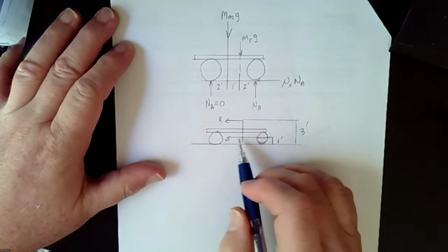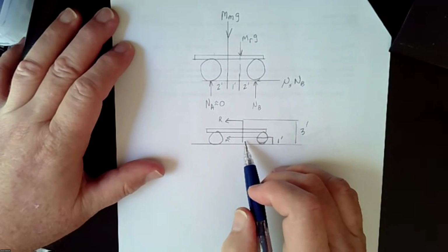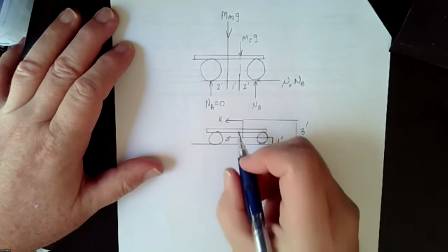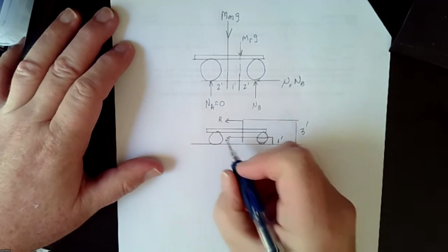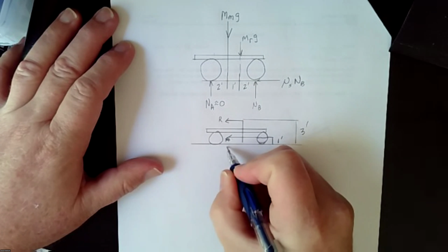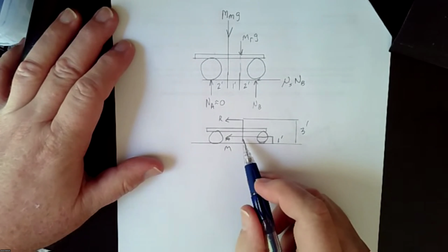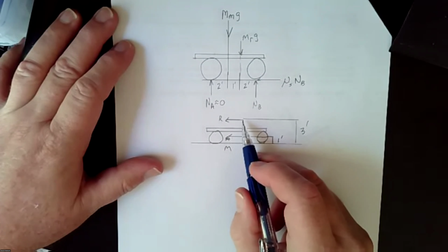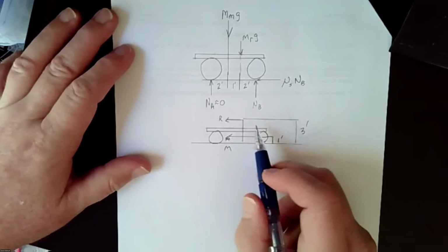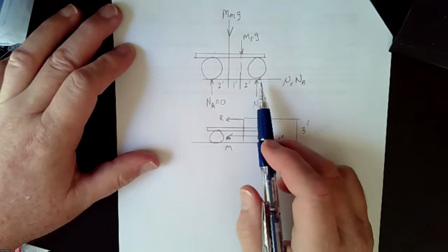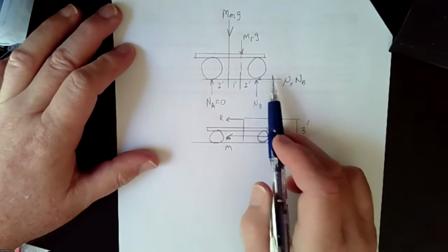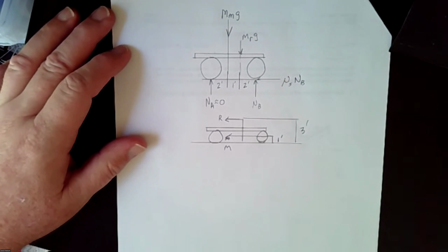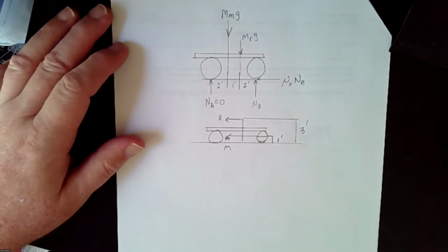So down here, it turns out that the center of gravity isn't as important this way as it is this way. So what I've drawn is the acceleration down here of the ATV. It's 1 foot off the ground, and the acceleration of the rider is up here at 3 feet off the ground. So think of it as you accelerate, the back wheel starts to skid, and the question is, what is the maximum acceleration that you can do.